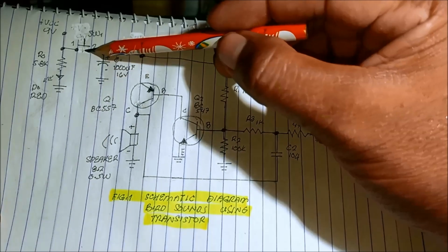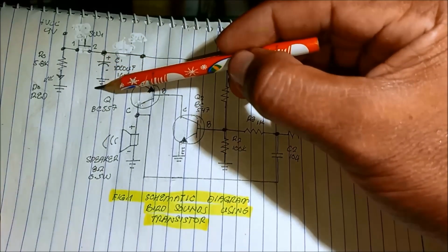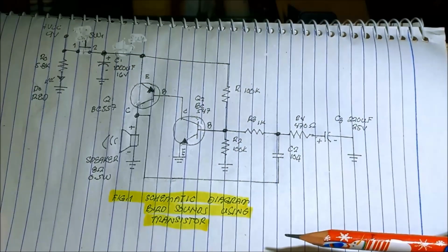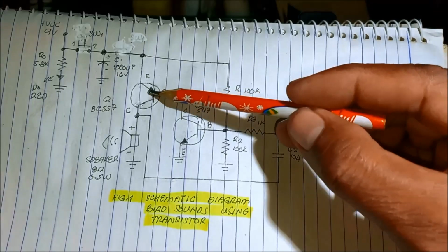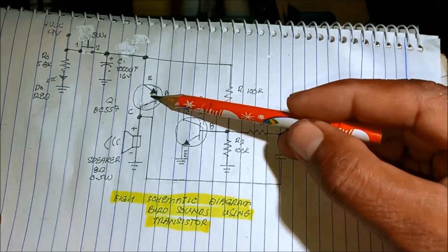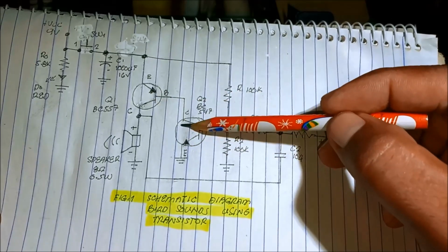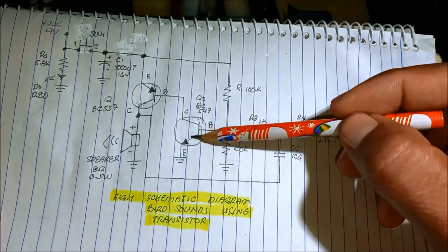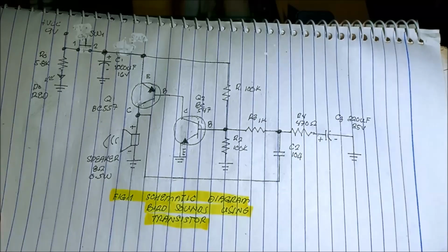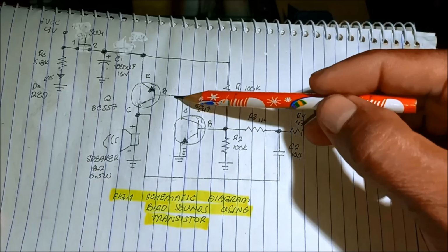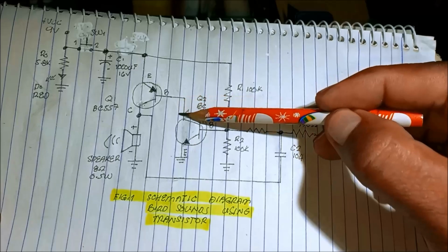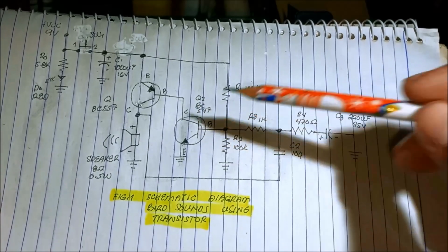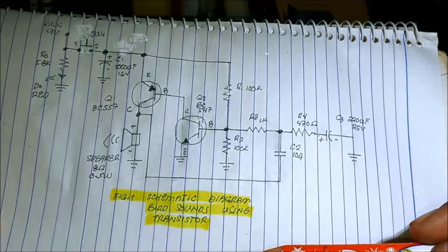So it is initially charging the capacitor and then discharging to the circuit. What happened now to this transistor? It is open because there is no current that flows into the collector emitter of the second transistor. We need the current to flow from base to collector to emitter to the ground of the second transistor.